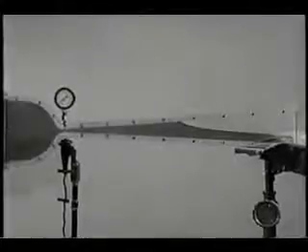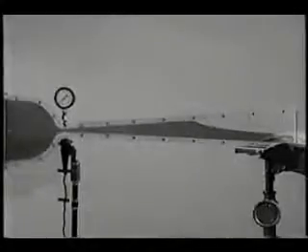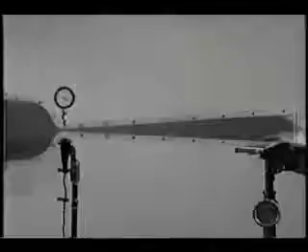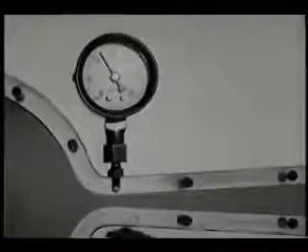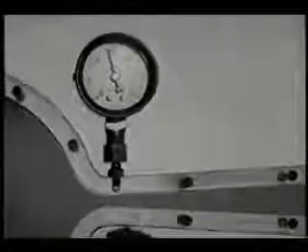In this experiment, water flows through a venturi that discharges to atmosphere. As we increase the flow, all pressure differences increase with the square of the velocity, and the pressure at the throat decreases. The gauge shows vacuum, and the pressure at the throat is now about 20 inches of mercury below atmospheric.